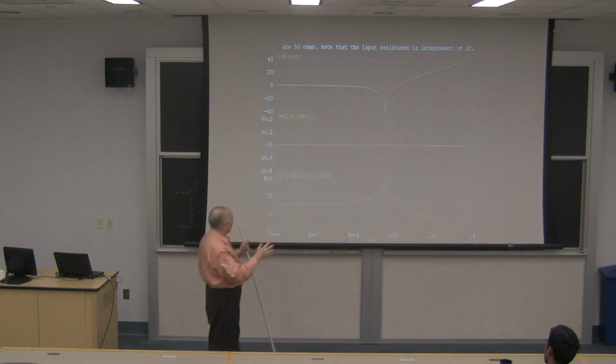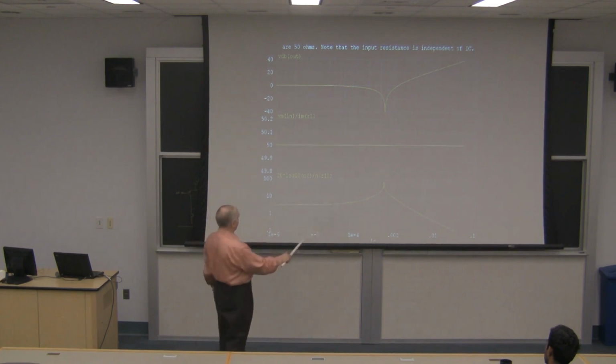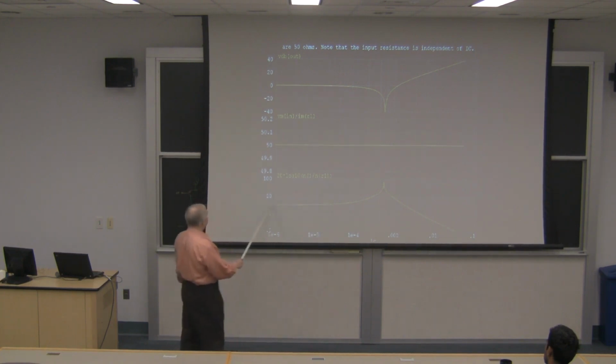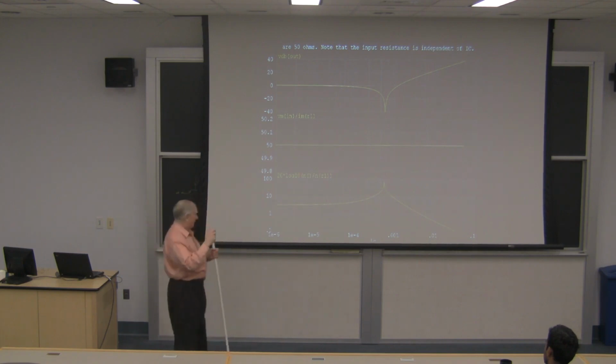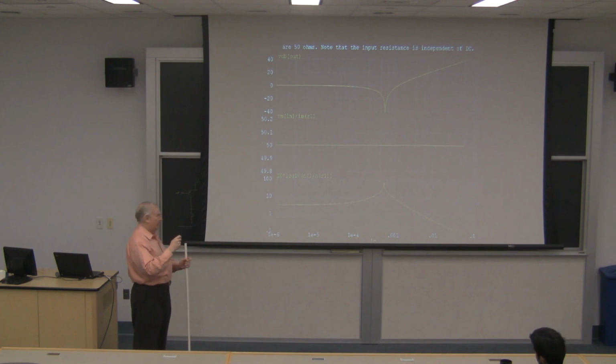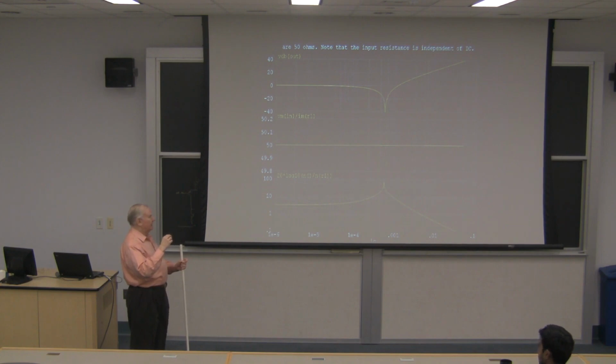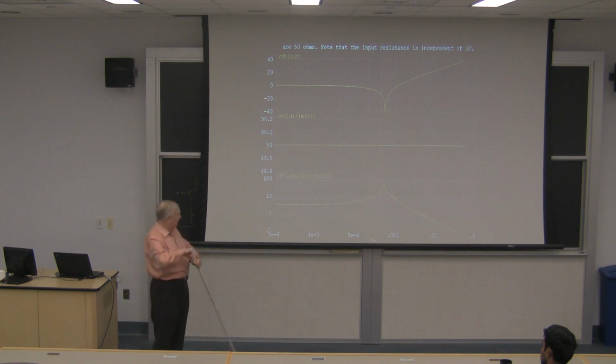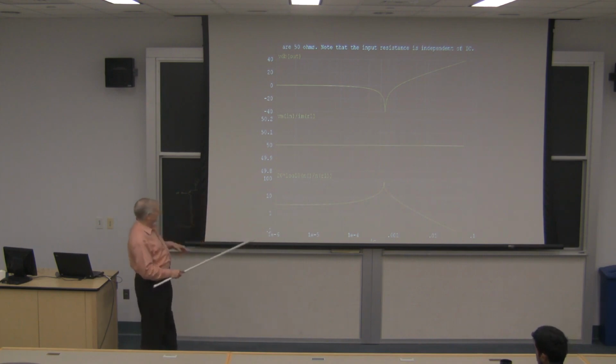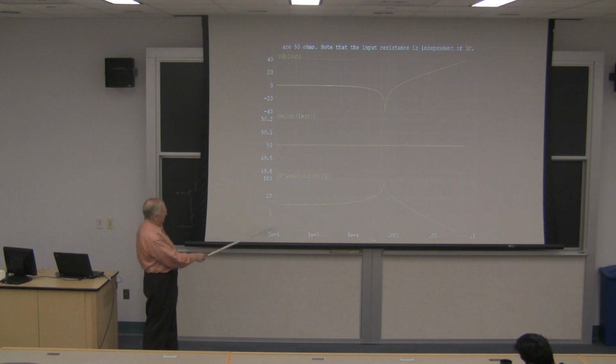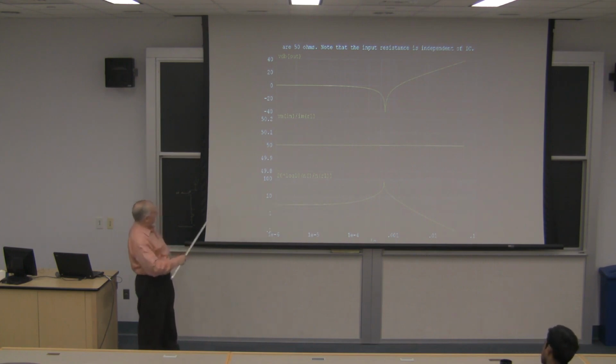So this is one way of thinking about things, because clearly you're not going to make this thing work down here. The reason the noise figure is 3 dB here is simply because eventually, at very, very tiny currents, the feedback resistor gets to be, how does it work? It simply becomes equivalent to a simple termination resistance. I'm trying to remember the mechanism, I shouldn't forget these things, but if you do the sums, I think it's better to do it yourself anyway. I can just push you in the right direction, let you get on with it. But you'll find it just behaves like a termination resistor with a noise figure of 3 dB down here, however low the current goes.